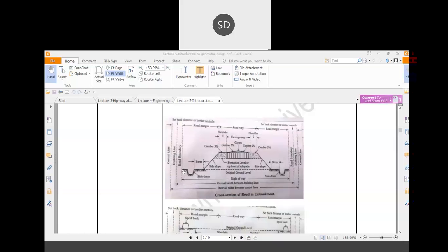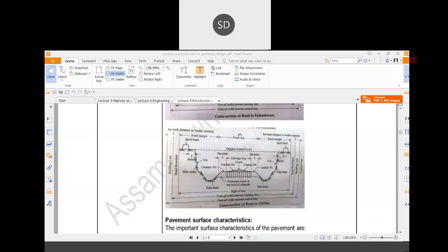That is your road boundary, the portion of the road situated over there, and different road features are there. And this is called the berm, that is the distance between the side of the pavement and the embankment. So just remember, camber is nothing but the cross slope. This slope provided in the transverse direction is called your camber.